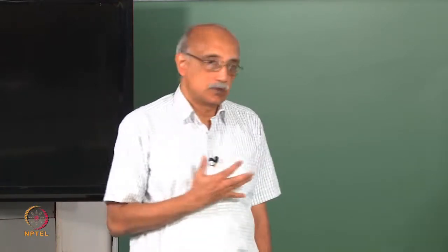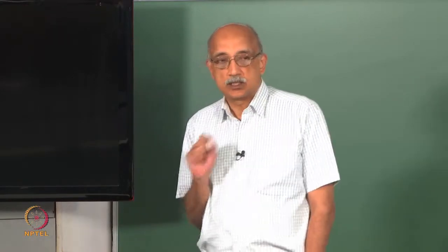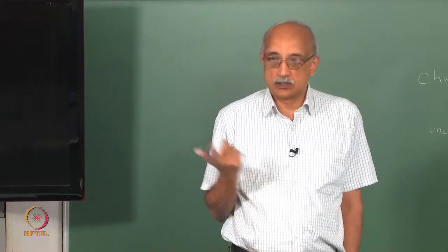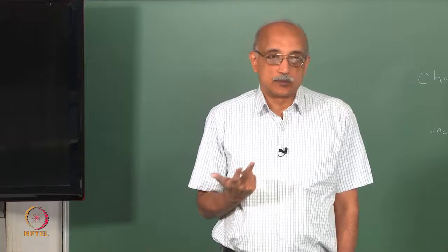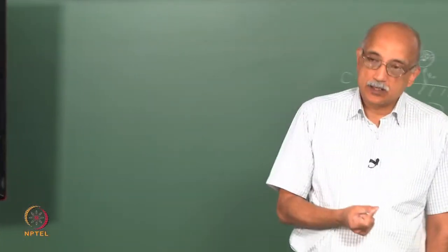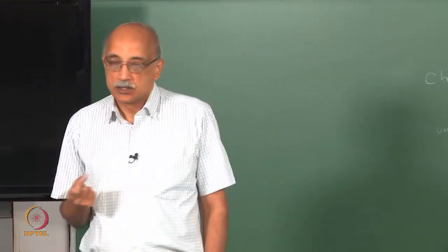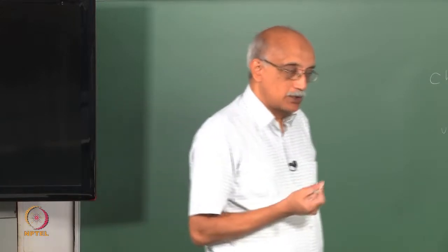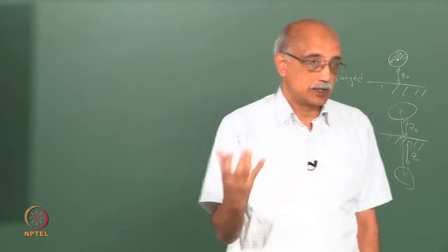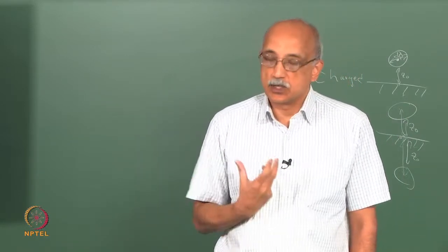What I really look for is that you understand the dependencies of the various forces on the critical parameters such as particle size, distance of separation, applied voltage and so on, because when you are trying to design a process, whether it is a mechanical operation or any other type of chemical process, the parameters over which you have control are things like the concentration of the slurry, the average particle size of the slurry and so on.